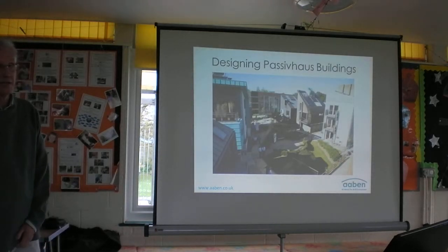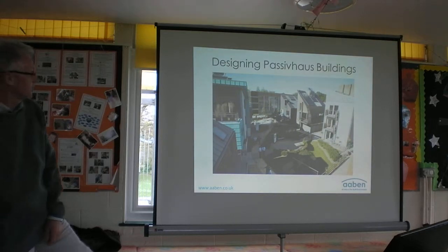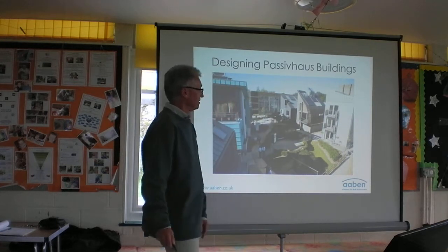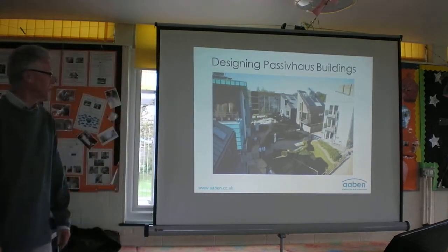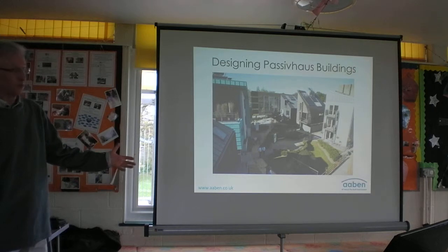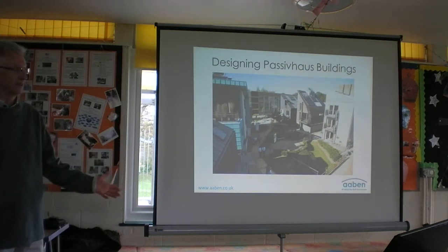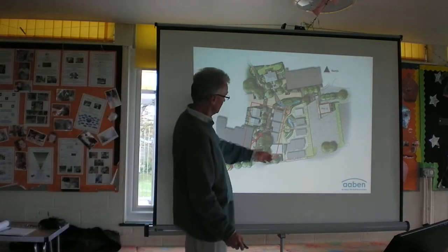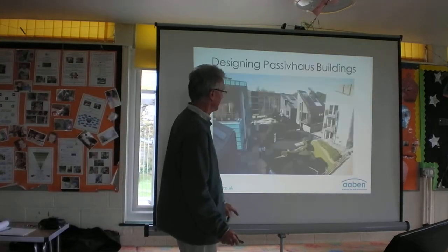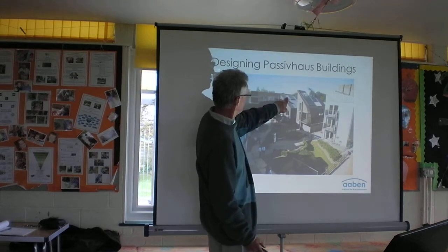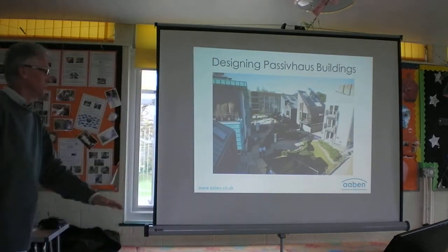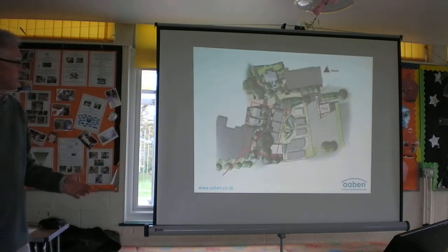That is the BRE Innovation Park in Watford, which some of you may know. That's Kingspan's Lighthouse, the first Code 6 attempt. That was interesting. Good try, but there's 1 or 2 things wrong with that site. That's the site. These are the buildings. This is south. They've just built them all in front. This has got solar panels on here, behind this house. Okay, it's a demonstration site, but that's bad design from a Passivhaus point of view.